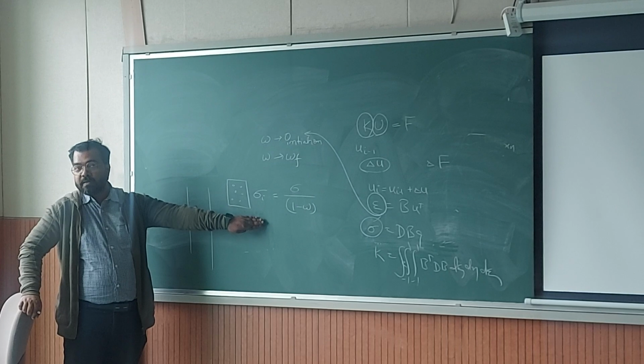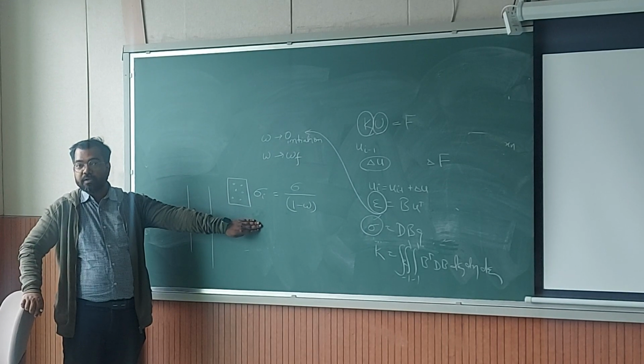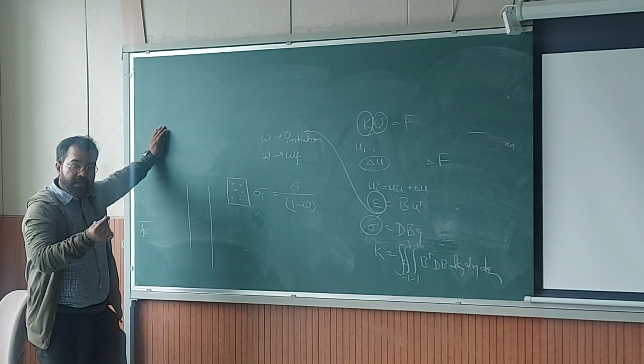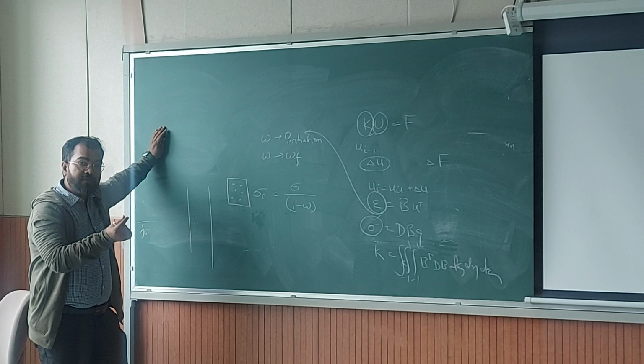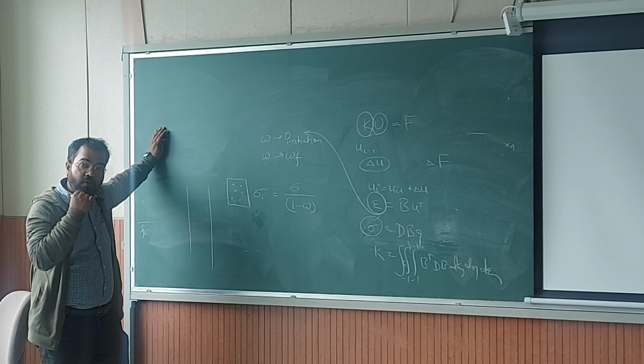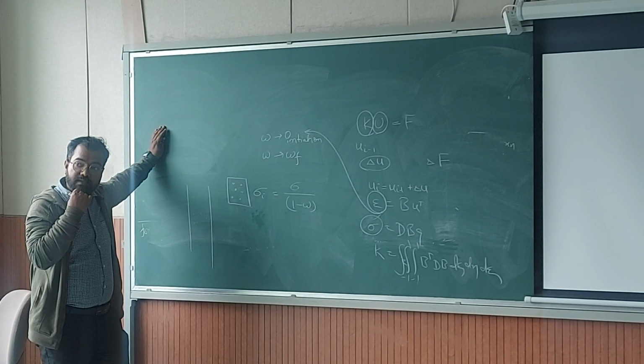We are just defining a parameter which is enhancing the stress, and by doing that it is degrading the stiffness. That's it. Omega really is not physically present anywhere. So you don't have these voids in physicality in finite element analysis. They really don't exist. Okay?